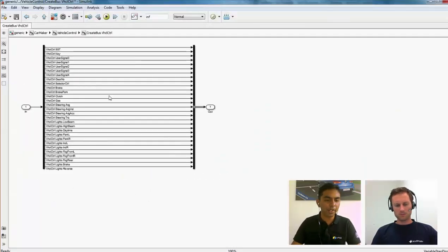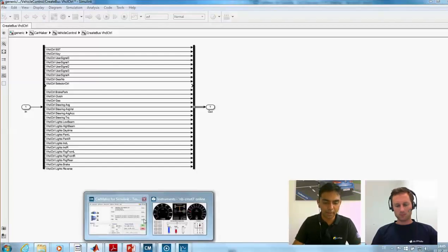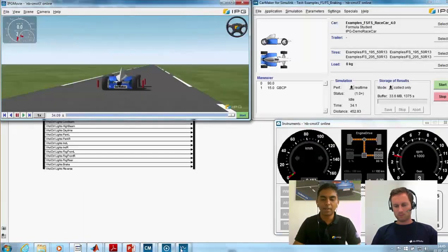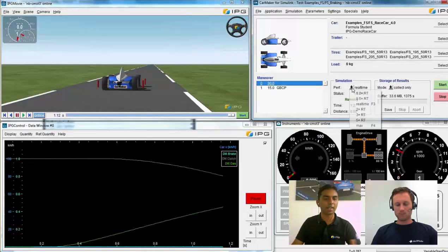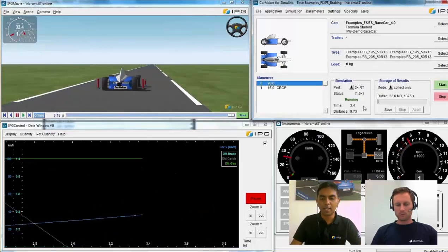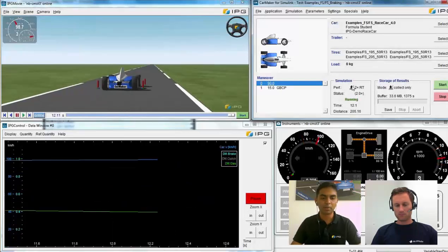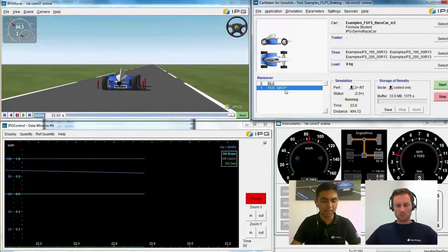So I can actually go in here and, for example, disconnect the brake signal. So my brake is disconnected. Now when I simulate my CarMaker model, I will see here that the car will be simulated. For example, I can run the simulation 2 times faster, so that I can see the result much more quickly. Accelerating, now he's going to brake in some time. He's braking, but the vehicle is not stopping. He's just coasting down. This is all because I've disconnected the brake signal here.